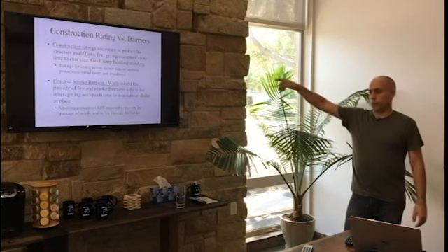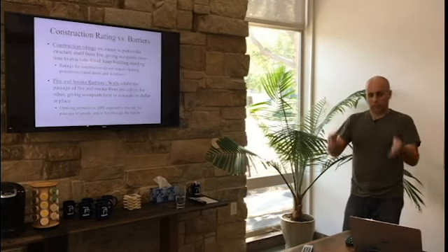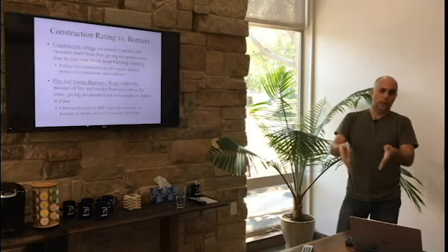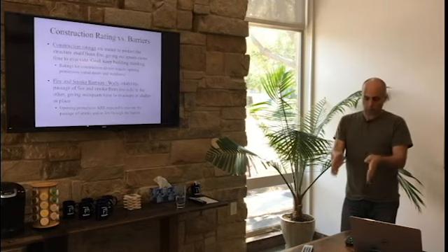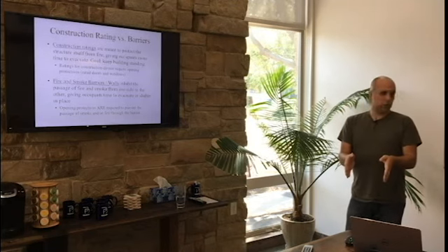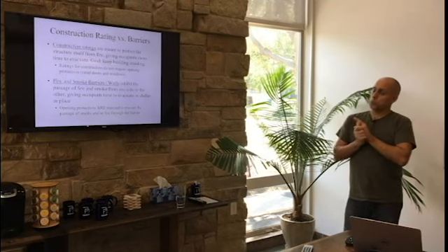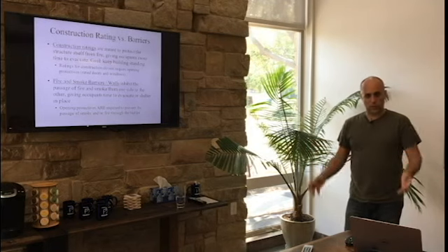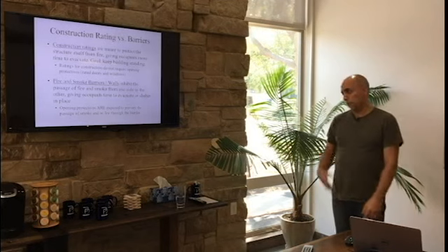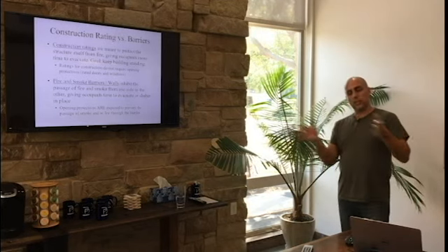Now, if we had a truss that went from exterior wall to exterior wall, they wouldn't even be rated. But because they typically bear on a corridor, it ends up being 1 hour rated from that perspective. So you have to treat it and keep the fire out of it. But you can let fire go through the wall. But they're supposed to be smoke partitions, say, on a corridor in a nursing home. You do have to keep the smoke out, but that's not a rating. There's no rated assembly for keeping smoke out. If you build it as a rated wall, chances are the smoke will stay out. But that's the defining line.